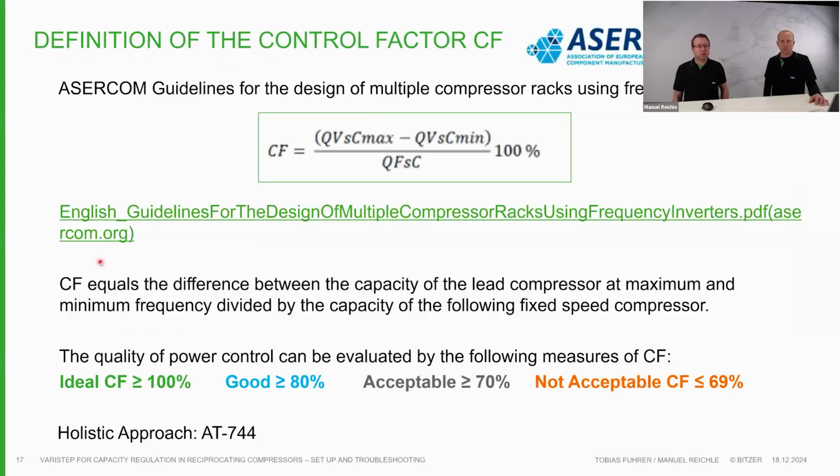So now coming to the system design, we spoke about the CF factor earlier. The CF factor is not an invention of Bitzer. It's coming from the so-called ASERCOM, which is the Association of European Refrigeration Component Manufacturers. Bitzer is part of it. All the other compressor manufacturers are also joining this. And together in this group, there were guidelines for multiple compressor rack systems using frequency inverters at that time. They did this recommendation, what you have to consider if you do this kind of system.